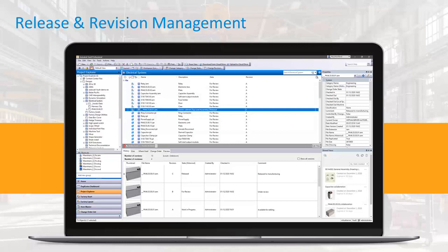So you might use the ABC. You might start with a dash or a 0. Vault has some that get you started, but you can always tailor it the way you want it. You can actually upload a custom revision scheme into Vault and it will take it from there. If your data already exists in legacy and everything is not a revision A, you can actually start in where that file is. So if the file is already in D, you can start with the next iteration at E. Vault adapts to the way you are already working.